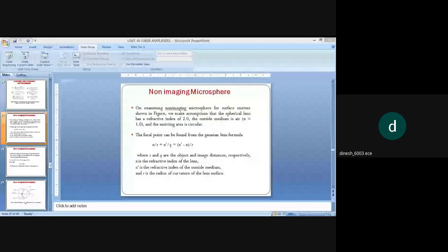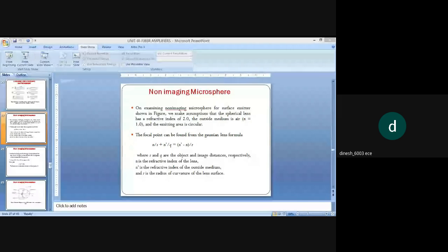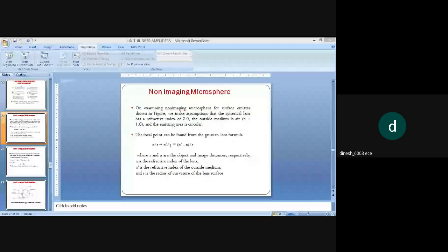Whatever we are doing is coupling on LED, so coupling and laser diode. The edge emitting laser has an emission pattern that nominally has a field width of 30 to 50 degrees in the plane perpendicular to the junction, and 5 to 10 degrees